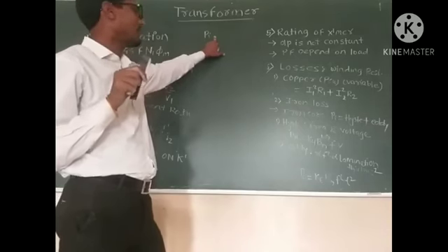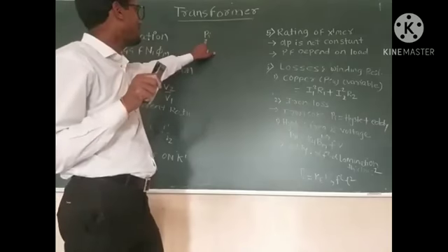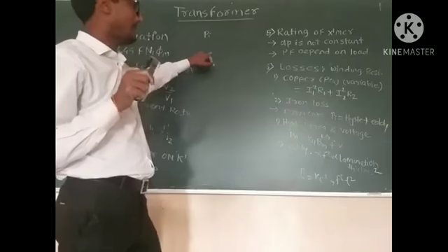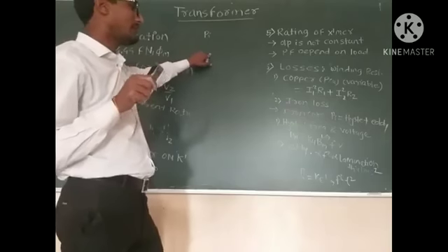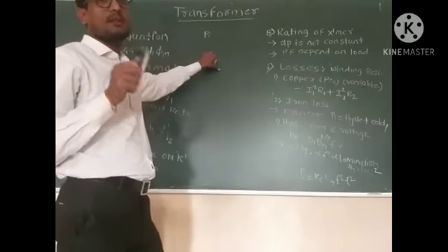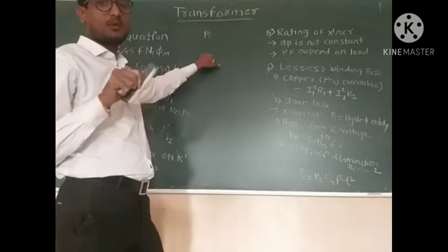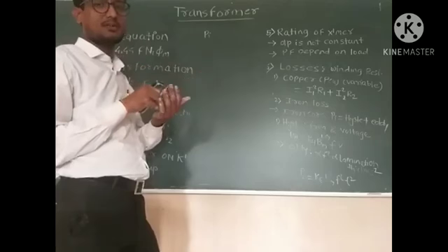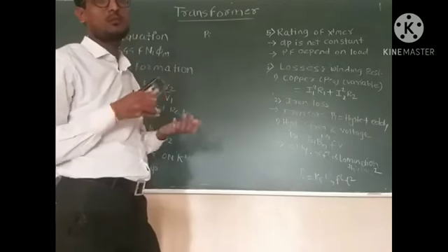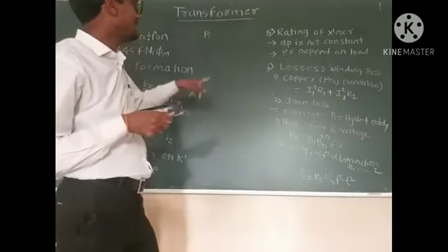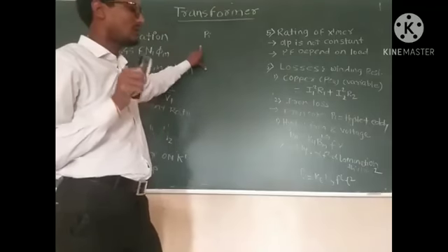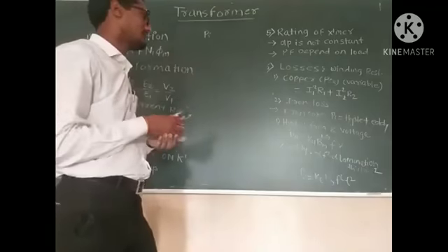After explaining this iron loss briefly, we found that this loss also depends upon the supply voltage and frequency. We cannot change the iron core, the frequency, or the voltage. Because of that, the iron losses or PI losses are called constant losses.